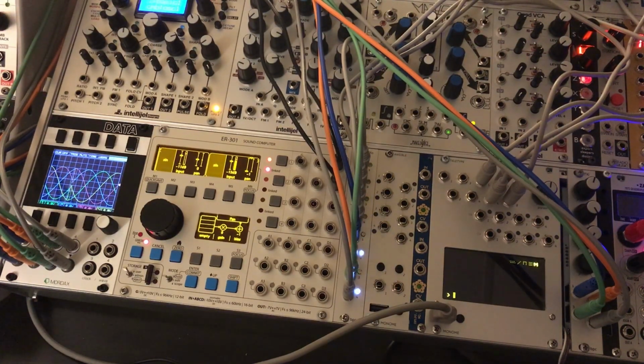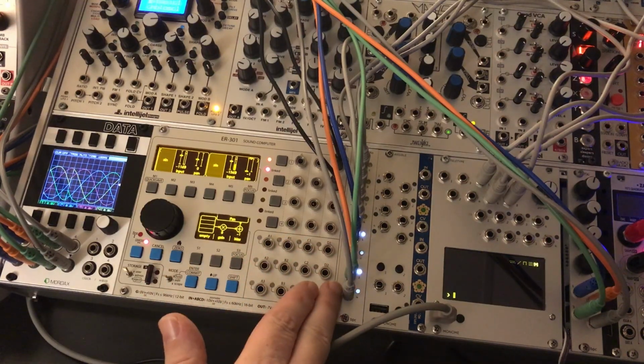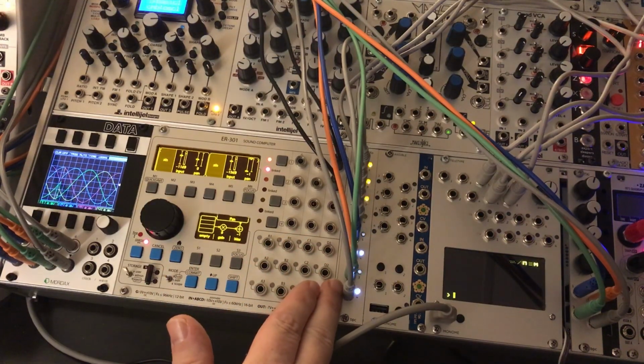These can be pretty handy for a number of different applications. You could send these anywhere, really. You could send these to a filter. They're used pretty commonly in time-based effects, such as choruses or flangers, to modulate the delay times. We're actually going to use it to control pitch or notes of 4 different oscillators, because I think that's a pretty easy thing to hear and understand what's going on. So the 4 CVs on the TXO are generating the Quadrature LFOs.